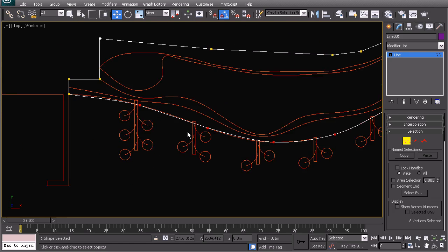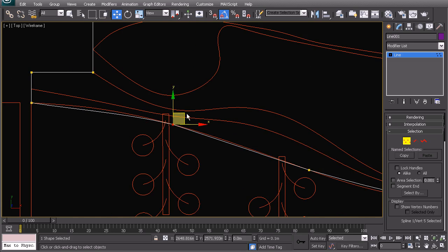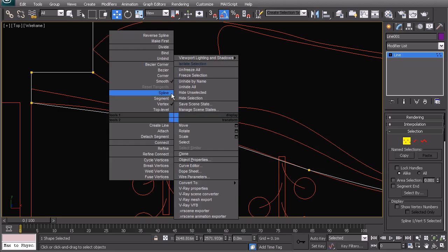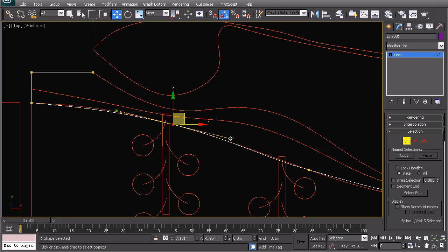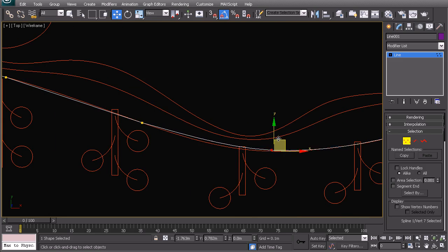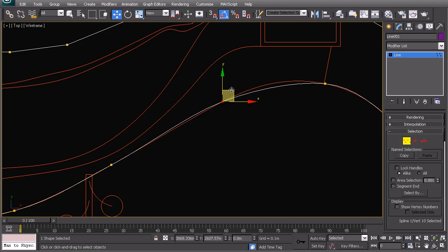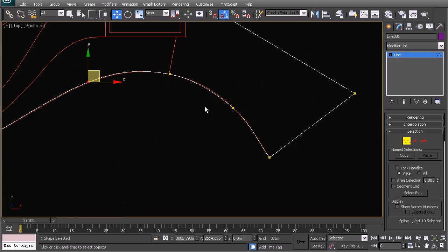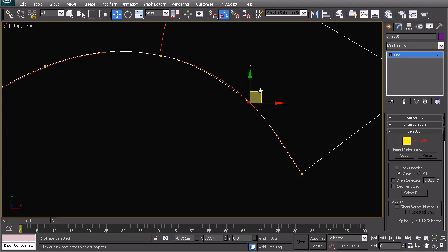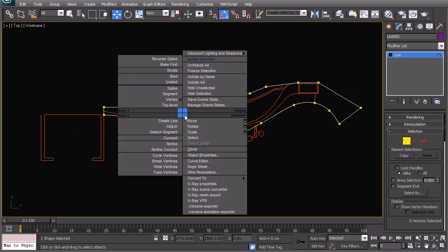You can either do that, or if you need more control, you can turn it into a Bezier. You can first see if smoothing works, and if the curves are not really looking great, then you can add more control just by adding that. Great, we don't have to be 100% correct. We just want to get the main outline to look more or less there.